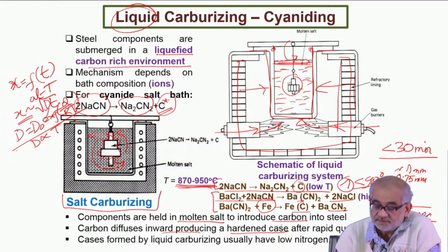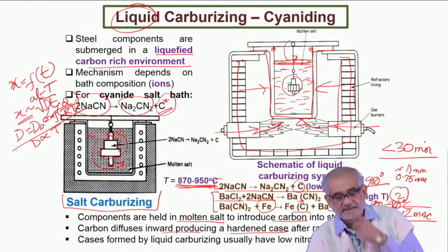And in fact, sometimes the immersed specimen after liquid carburizing can be directly lifted and quenched into coolant, and there is no separate heat treatment needed in that case.